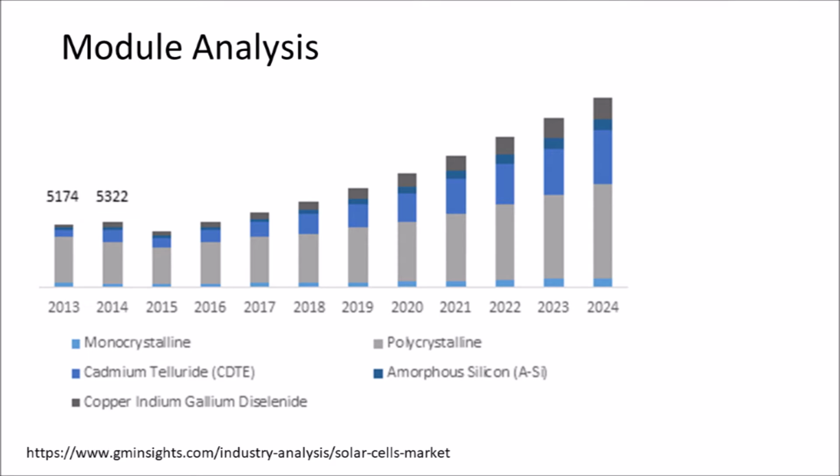With different cells going onto different modules out of the same production batch, that is why on a module specification sheet, there will be different specifications for slightly different solar wattages, all of which have the same dimension. The cell sorting creates all these different wattages out of the same production batch, and they're priced differently as well.